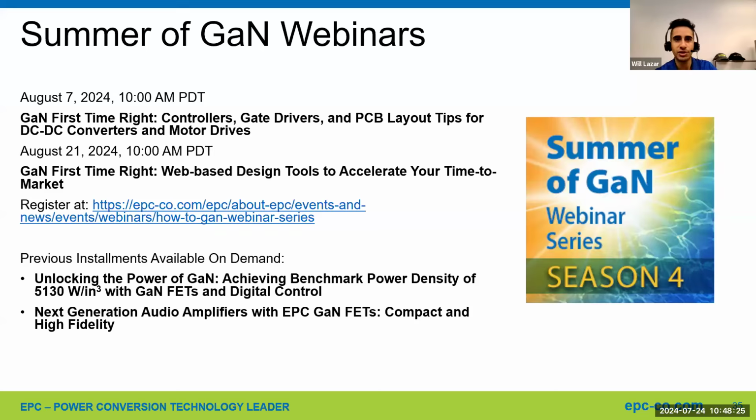Tiziano, our first question here. Schottky diodes above 100 watt have PN junction parasitic, hence a bit of QRR. Have you tried SiC diodes?